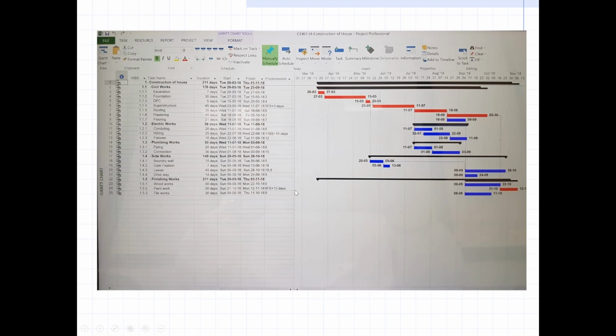So first we prepare and assign the WBS, and under the WBS we make activities and assign durations to those. By this way we prepare the schedule. Inshallah, when you practice on Primavera, you will get the idea how to work with these things. Also we assign the calendar to each activity. So we decide the calendar, the working days. Suppose in Saudi Arabia, we don't work on Friday or Saturday, so it's 5 days a week. We can set the calendar.